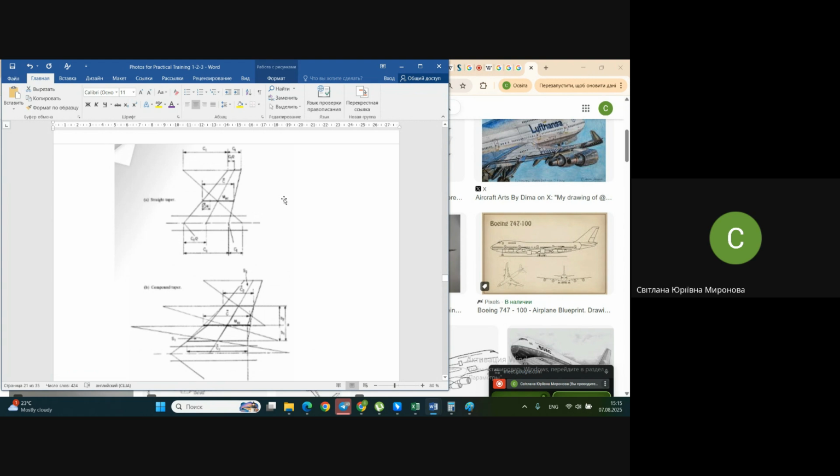In case you'd like to pass from mean chord to your wing, if it's a swept wing, it means that you need to use one more relative dimensionless coefficient, which characterizes the relative narrowing of the wing, and due to this, you may already understand absolute values of root chord and tip chord. That is geometry of the wing.